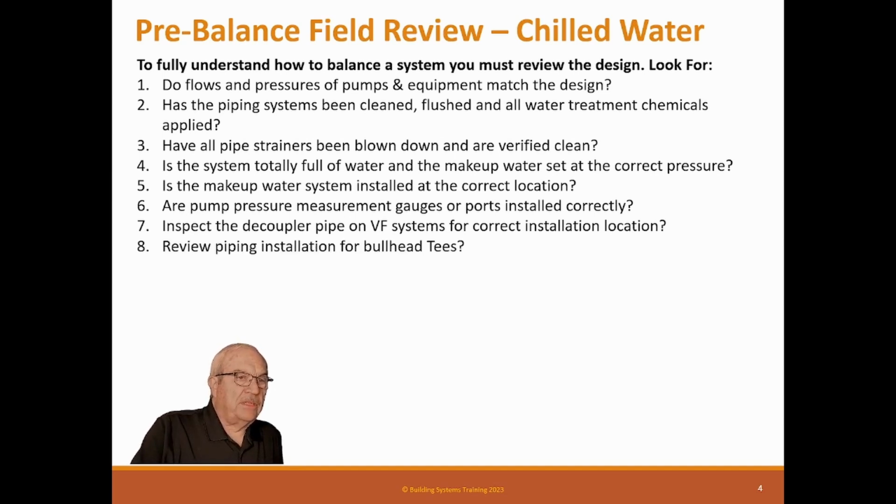Review pipe installation for bullhead tees. There should never be a bullhead tee on the job. A bullhead tee is a pipe that has water flowing into the side lateral of a T and going both ways, left and right of the T. That's a bullhead T. Or even worse, if you have water flowing from the left and the right, crashing together and then expected to combine and go out the side outlet of the T, that's a bullhead T.